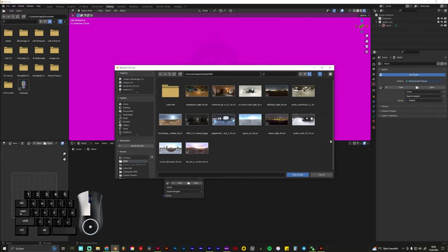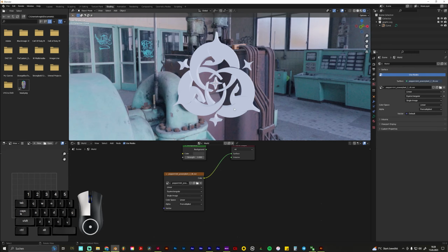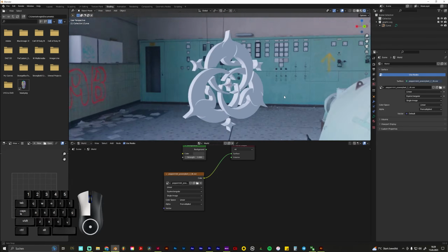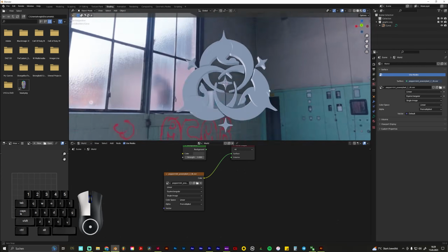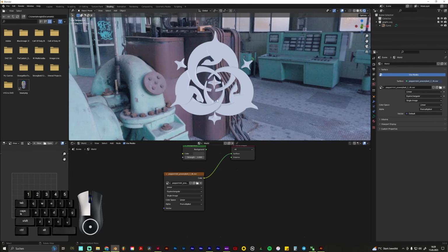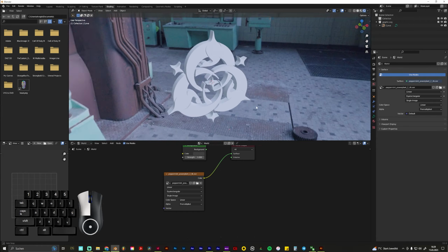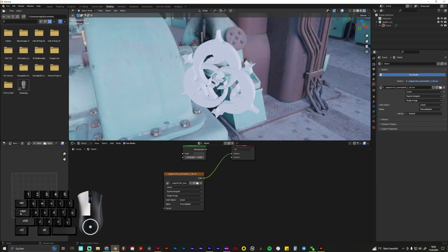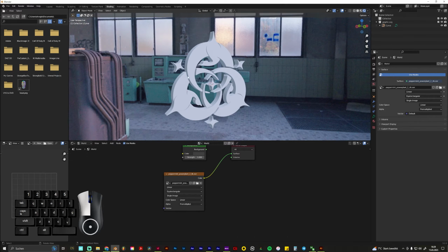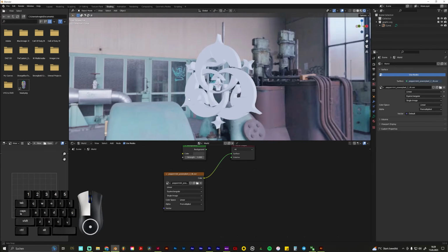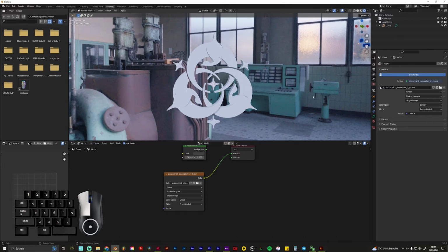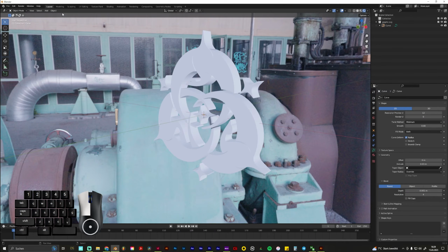It's simply a super stretched big photo, and Blender turns it into a whole environment. Yeah, I think you got the idea. It's perfect for reflections. In this case you don't see any reflections because right now it's matte and not glossy, but we will change it in the next step. We go back to layout.